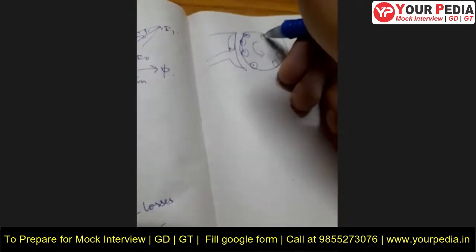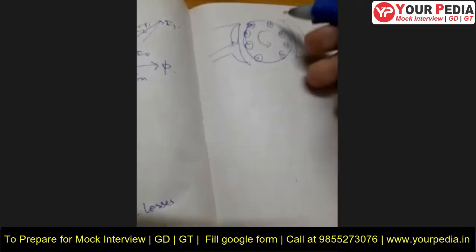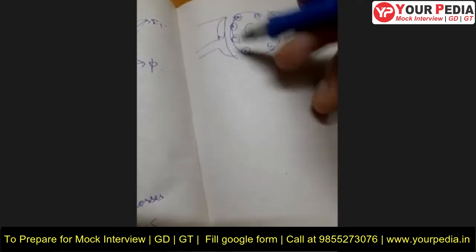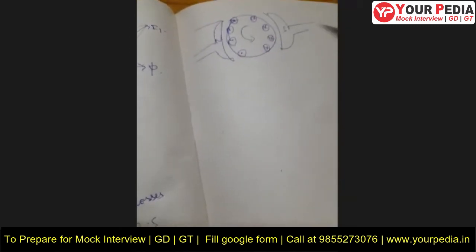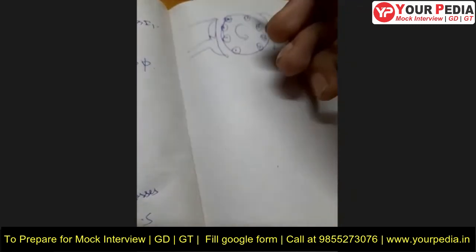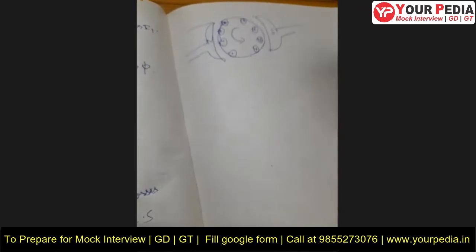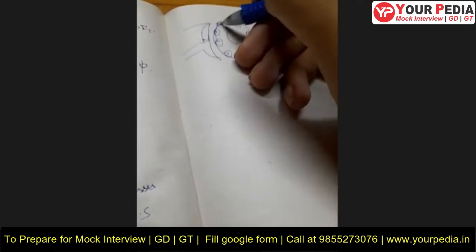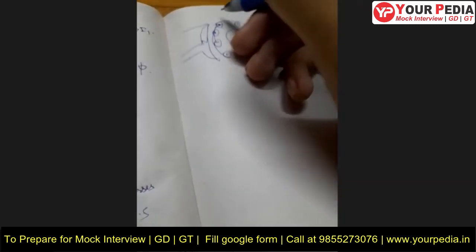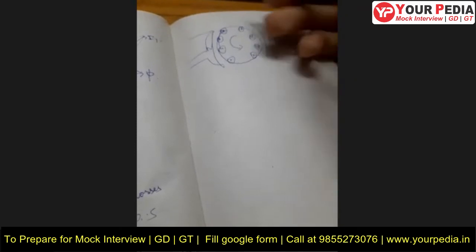This will be the direction of induced EMF, sir. If the load is connected, current will flow in the same direction, sir. As currents flow in the armature, the armature also develops a pole pair, sir.